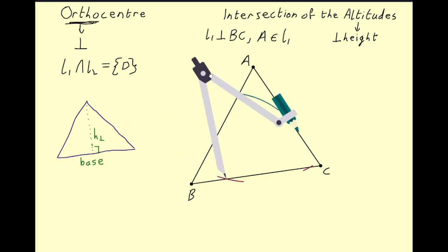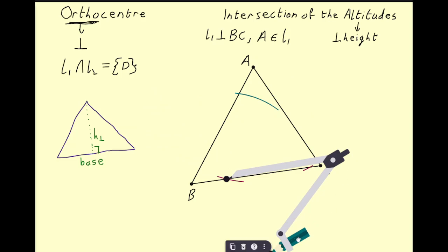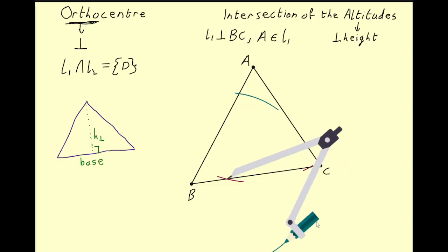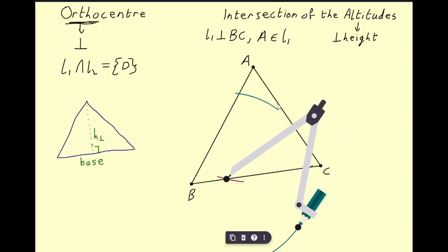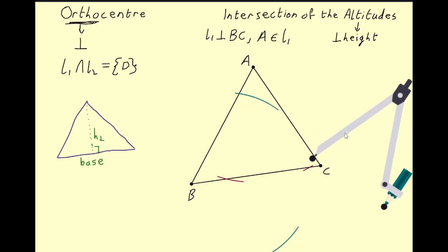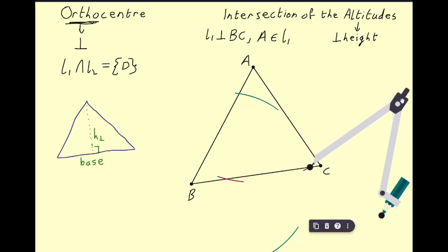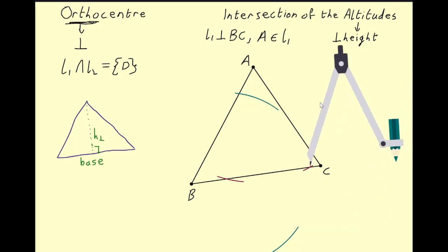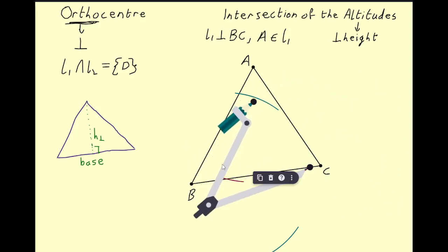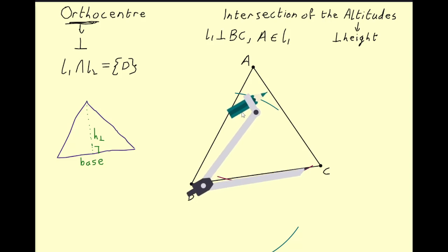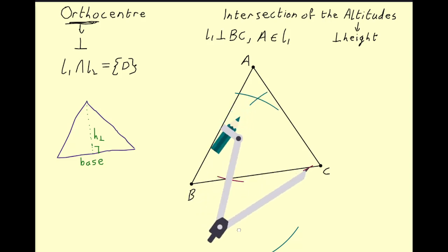And we're going to swing our compass around, and we're going to do the same thing down here. It's not a great idea to have continuous arcs going here. It makes the construction very messy. If you really want to, there isn't anything technically wrong with it, but it makes it difficult when there are so many squiggles on our page to keep track of what it is we're doing. So we keep the compass at exactly the same size, and just do a perpendicular bisector.